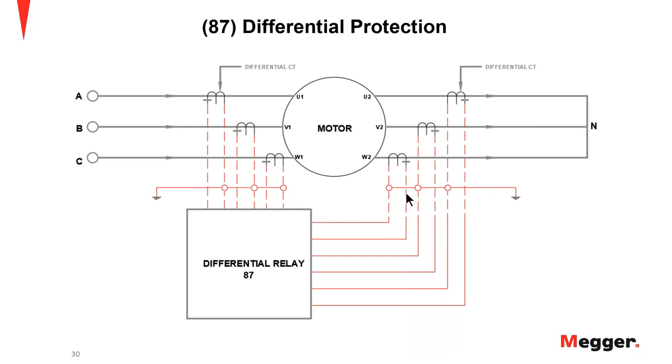If these things are hidden somewhere, then of course it just makes life a little bit more difficult at that point. But yeah, you can. There's not really a set rule. Do I need to ground the yard? Do I need to ground it here? What we want to do is just make sure that we have access so we can see it, and make it to where it's only grounded once per CT circuit, and we don't have any double grounds in here. So there we go. All right, thanks, David.